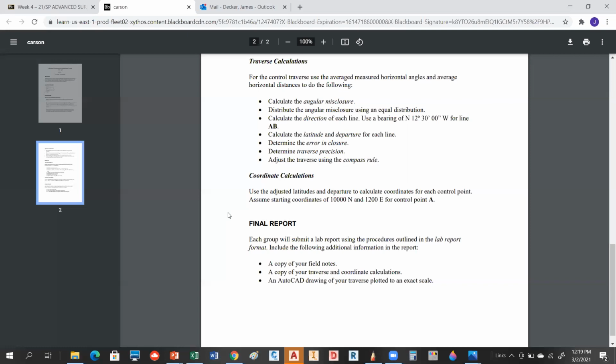Now, when it came to distance, what do you think was the distance issue? Anybody? You can just have a little bit of swaying of the prism. Absolutely. I mean, you're holding that prism and you're assuming that the bullseye bubble on that prism is adjusted properly, right?